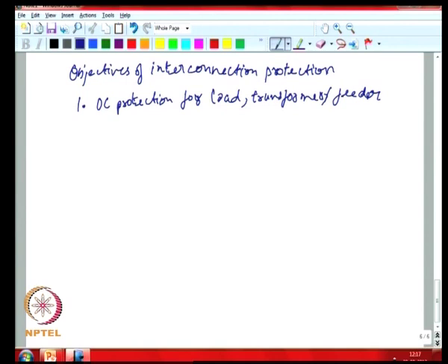You want that particular breaker to ensure that, now that you have two sources, you could have the grid causing overcurrent damage downstream into the facility, or potentially the DG causing overcurrent damage upstream out of the facility.